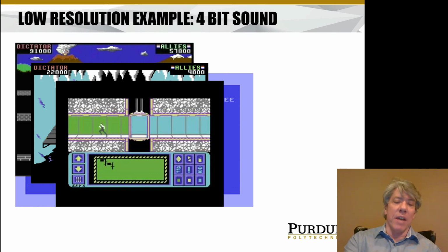So I've got a video where you can actually hear that, and the reason I want you to hear it is not for the sake of my nostalgia, but for you to hear what lower resolution sounds like, so you can begin to understand it. Often low resolution, either discretized in time or in amplitude, is completely acceptable. It just depends on the process and what the process needs in terms of time and amplitude resolution.